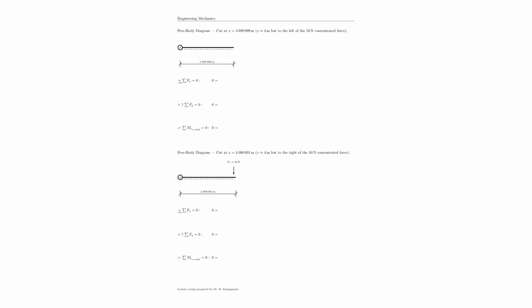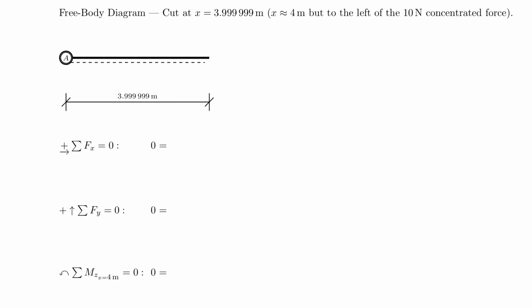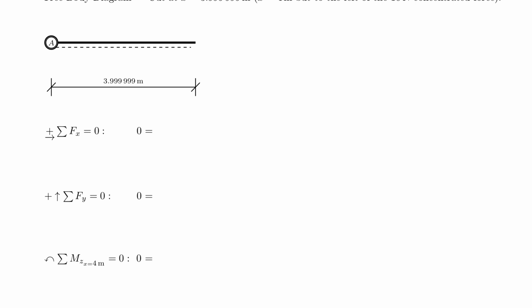All right, so now I have prepared something for you. Actually, the first 2 cuts are prepared. So let's take a look at the very first cut here on the top. As you can see, that cut has a length of 3.999999 meters. Remember that the first thing I need to do is bring in my external forces. So what external forces did I have? I had a support reaction here that was pointing upwards.